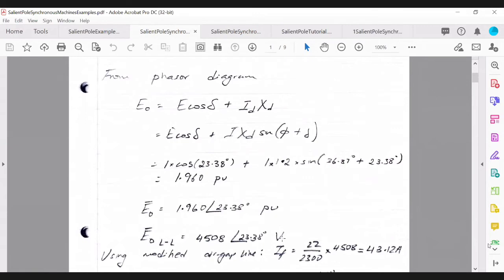Now the line-to-line value will be different from the phase value, depending on the type of connection of the motor. So there'll be the factor of √3 that comes in. Did you check that? No, I forgot. Yes. So there are two things. There is EB and there is √3 that you need to consider to basically determine your line-to-line value. Okay, thank you, sir. Okay, sure.